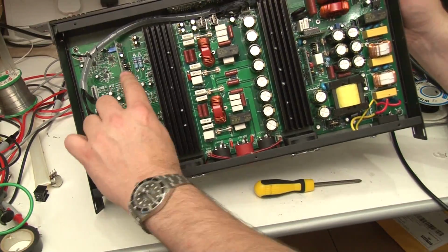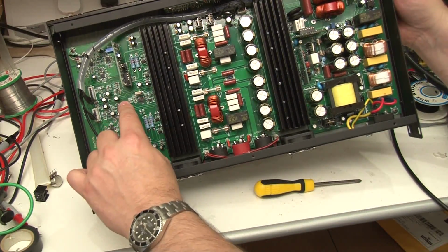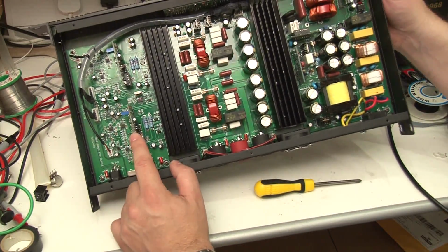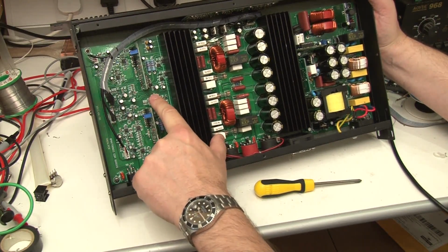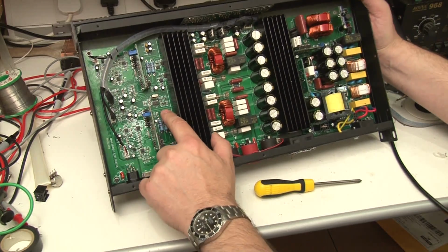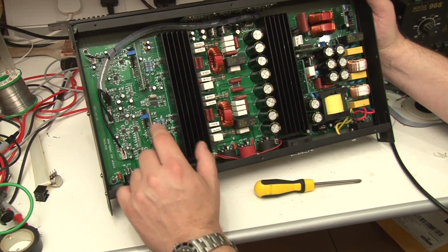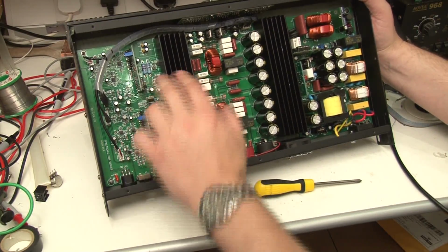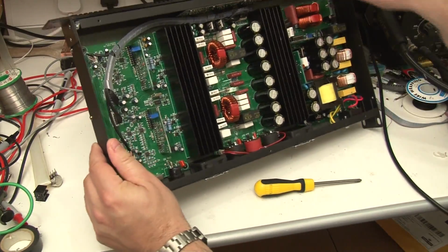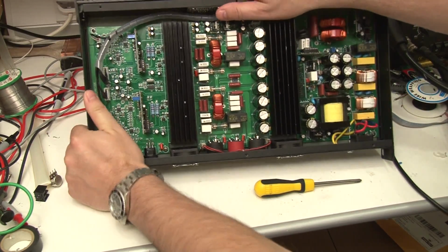So these boards here will be generating that PWM signal. They'll have the comparator on it and the ramp generator and all that kind of stuff. There's also a crystal there, which I guess is the source of the clock, and that's obviously common to both of these boards. And then under here will be the 4 switching FETs. Now I'm guessing there's 4 switching FETs. I don't know if I can catch it on camera.